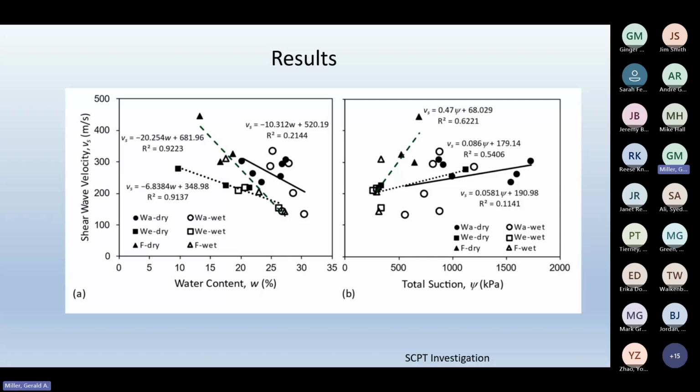And again, you may have to consider overburden pressure in that analysis because that's going to affect your shear wave velocity. You follow me? So you can begin developing correlations just like I did with the SPT N values. Start plotting shear wave velocities versus water content for different soil types, and you'll probably see some trends. There'll be scatter, but you'll get some sense of how things might change.